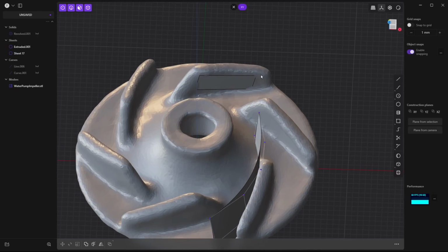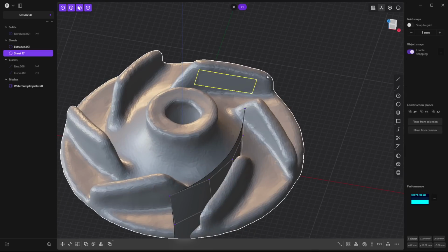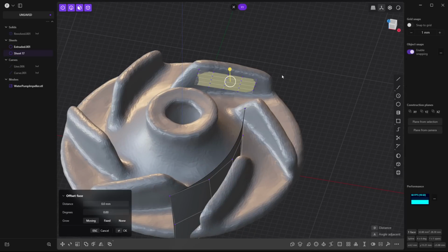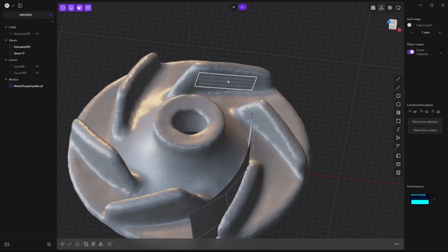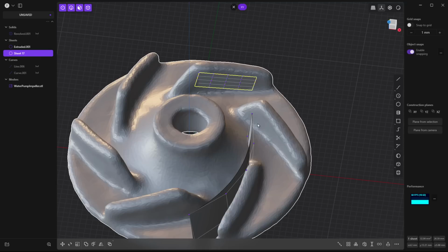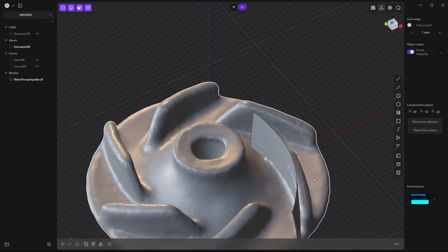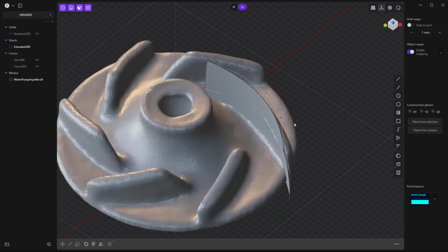So the problem with the constrained surface is, one, our reference isn't great. Two, we have all these rounded corners and edges that won't let us properly overbuild the surface. If we try to adjust this with, say, raise degree, we can still do that and move it around, but it's already got more subdivisions in it than a simpler solution of just extruding a surface and then tweaking it with raise degree. So this is an option, and it may come in handy with certain types of models, but in this case, it's actually going to be more problematic than it's probably worth. So that's why I decided to use the extruded surface option rather than using a constrained surface.